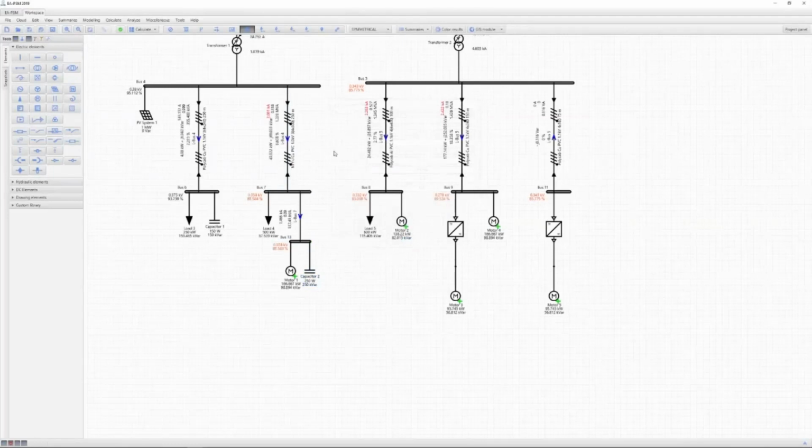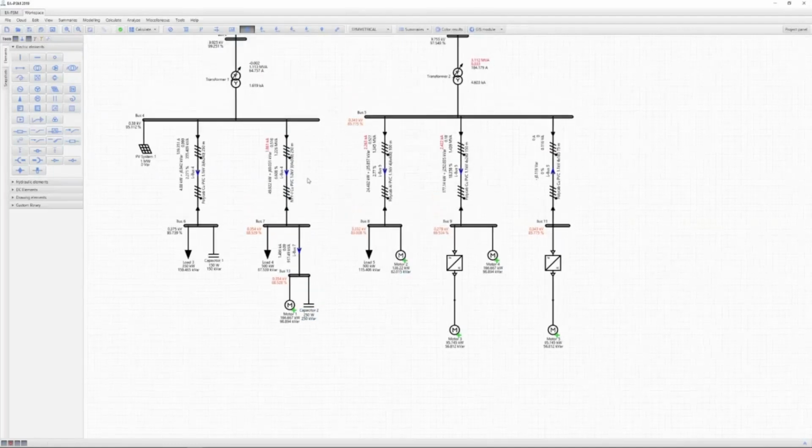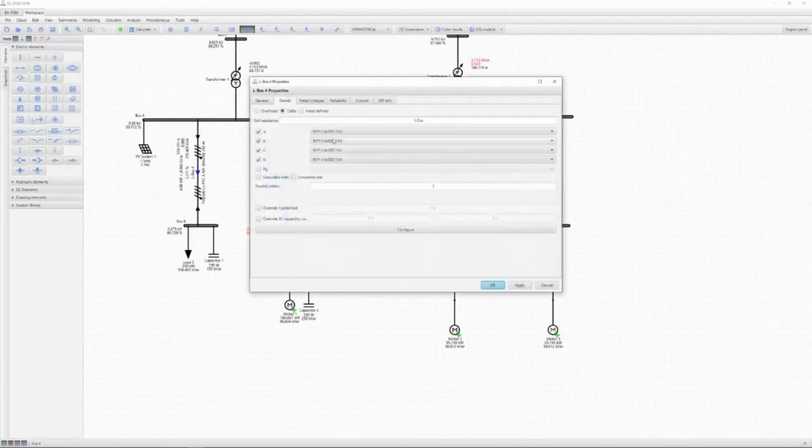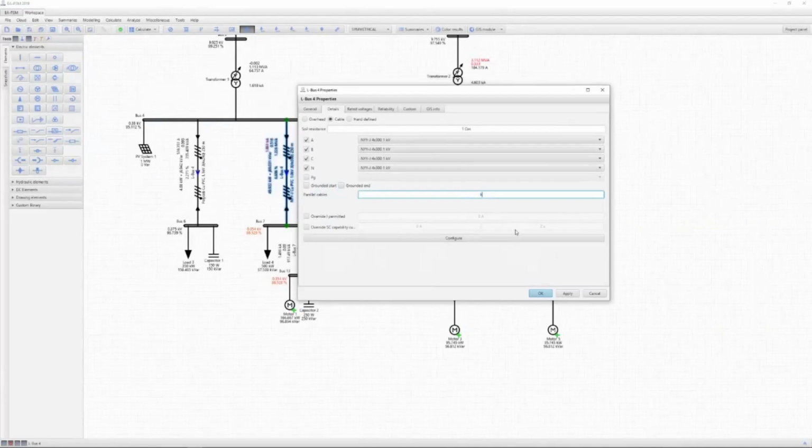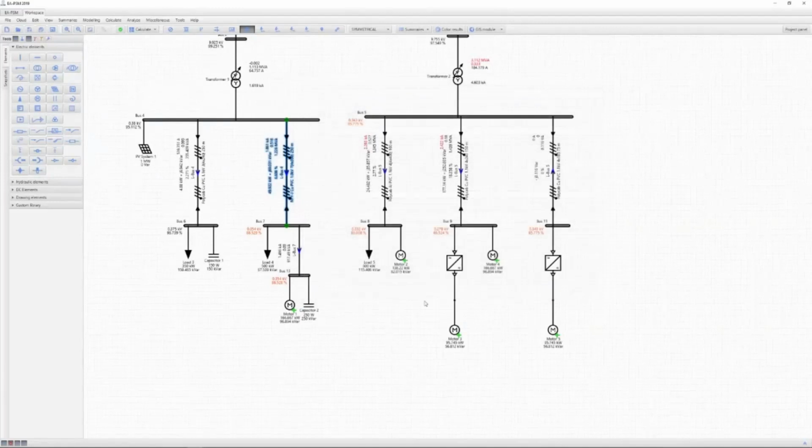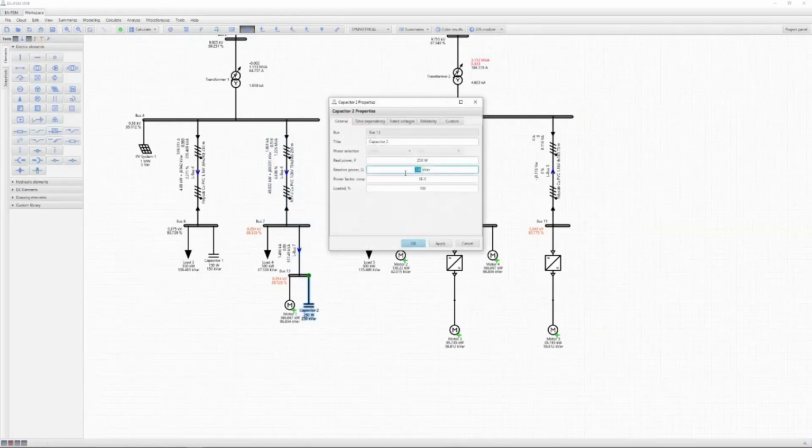Well, as we can see, it slightly reduces, but at this point, to compensate the reactive power, we should just double the grouped cables. So in this situation, we should add 3 or even 7. 7 is enough, so that is all right. And as we can see, the voltage level is slightly dropped at the bus bar. So that thing should be taken into account. As we can see here, we're generating a lot of reactive power. That should be compensated. We can add even more.